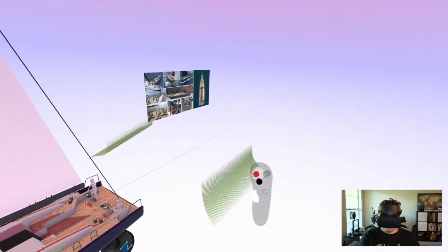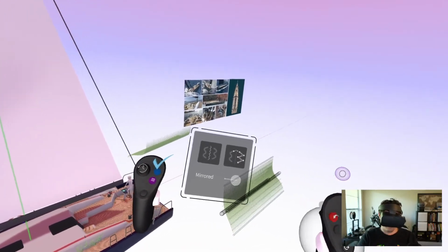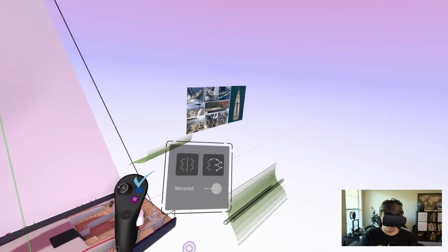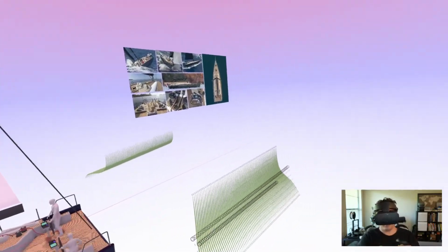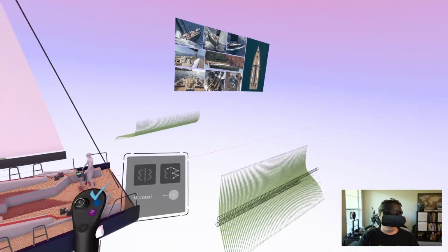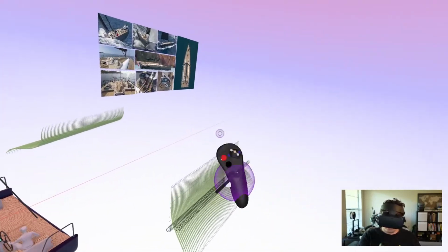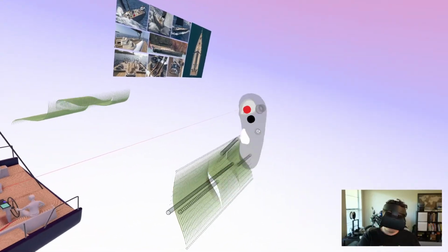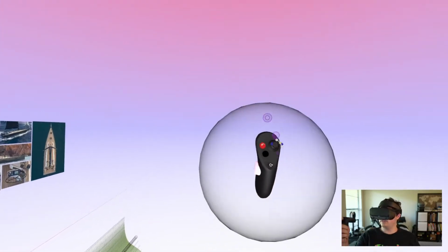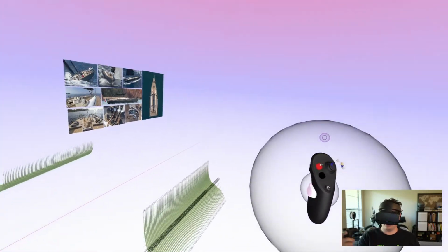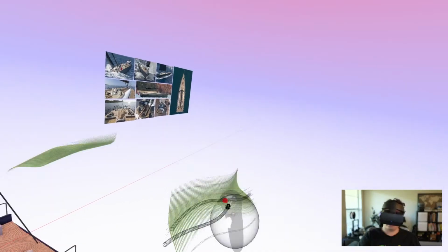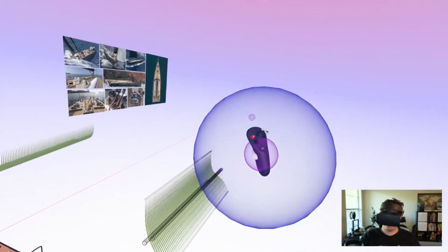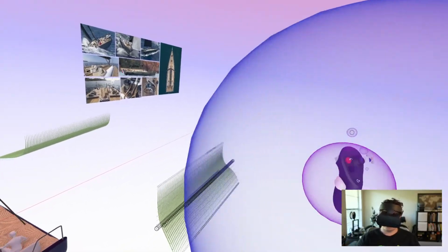But if I select everything and I hold down the edit mode button, I get this little menu here and I have a few more options. I can turn it off, whether it's mirrored. I can also unify the mirror so I can actually mirror all of these objects at the same time, which is really helpful. I can also edit them all at the same time now, so they're all in edit mode. And what's cool is I can do that soft select feature like I mentioned earlier, and I can grab all these and pull them all around and manipulate them at varying degrees of manipulation.